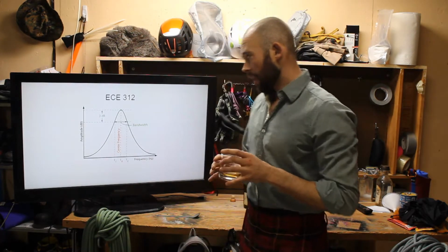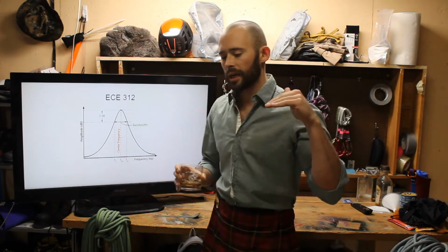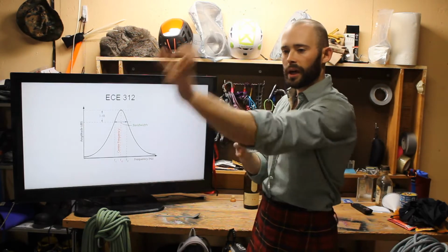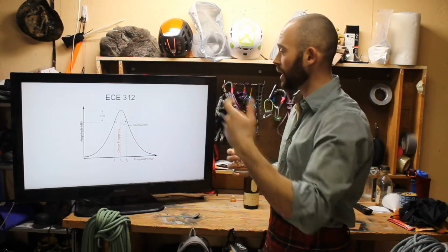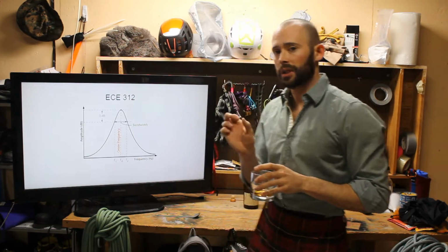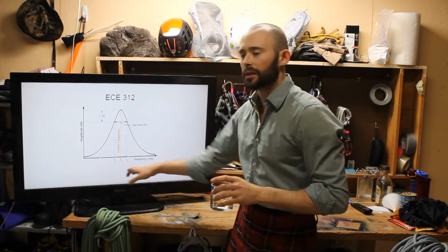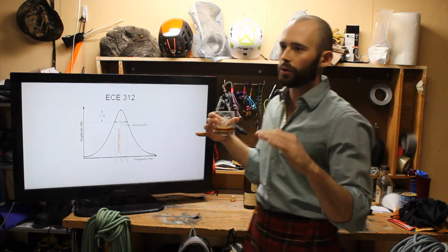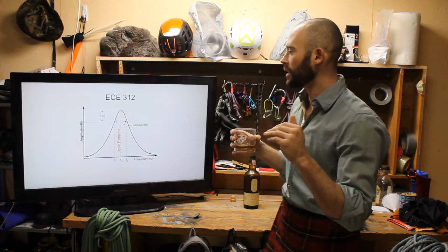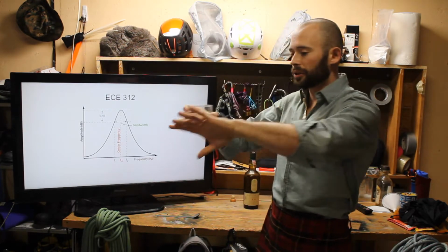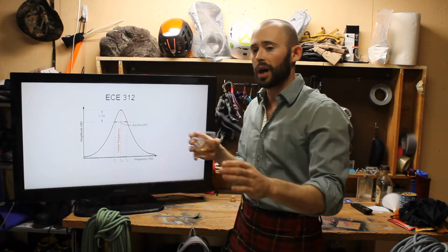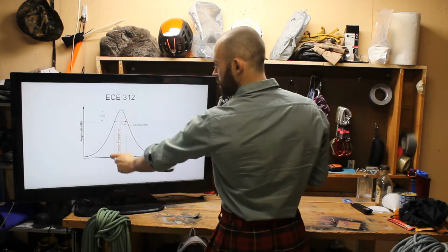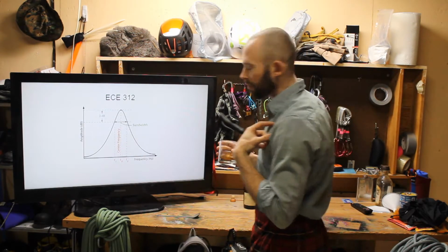So as our frequency is pushed into the system, it is then put onto a carrier frequency, which is the 900 megahertz from GSM. So that center frequency is going to be centered around F0. And this graph shows the general shape of the filter that we need to use in order to filter out all of the noise and all of the frequencies we do not want from other cell phones, from other cells, etc. And we just want this part of the graph because that's where our information is.